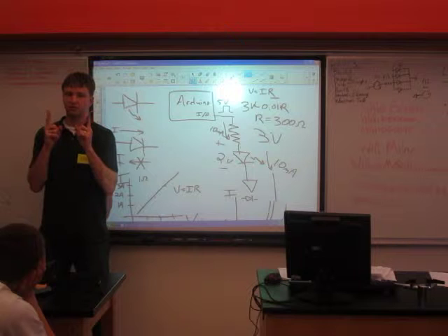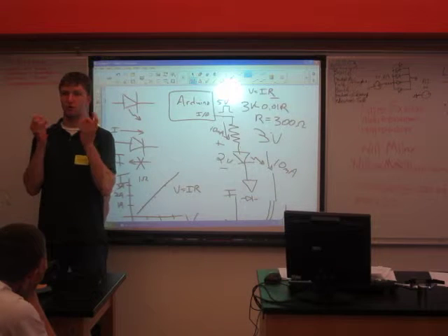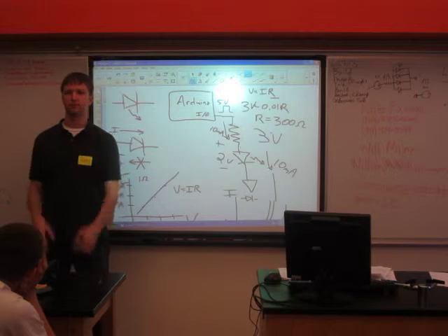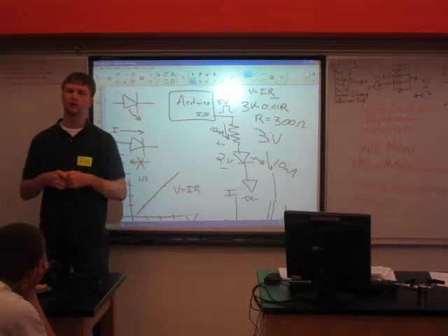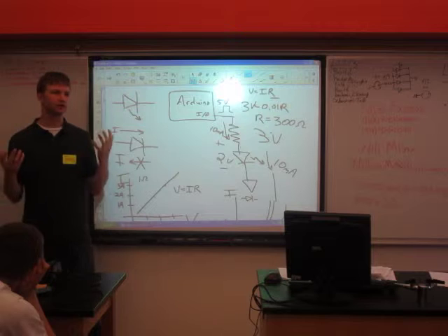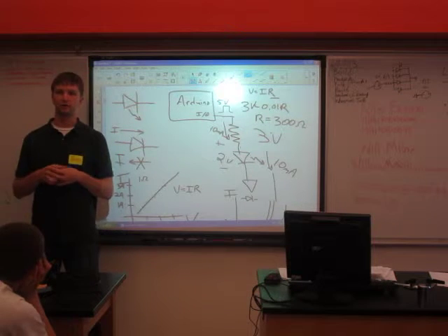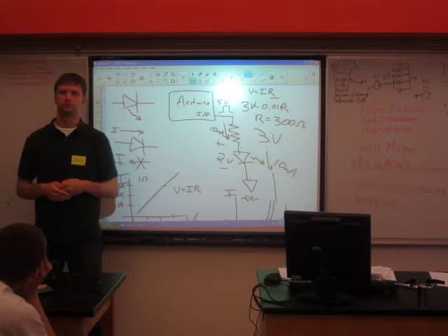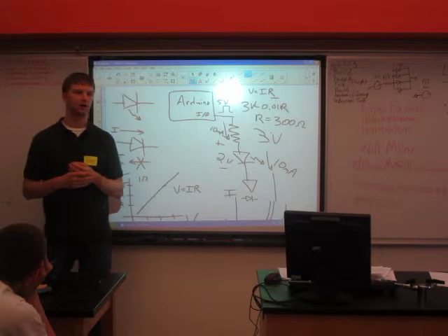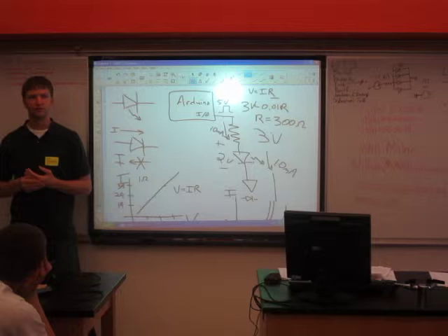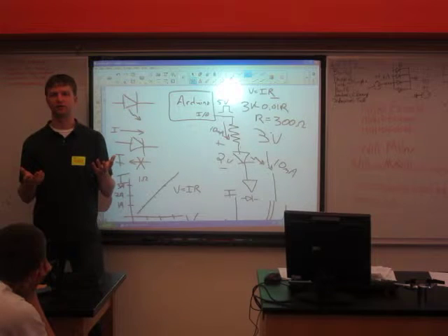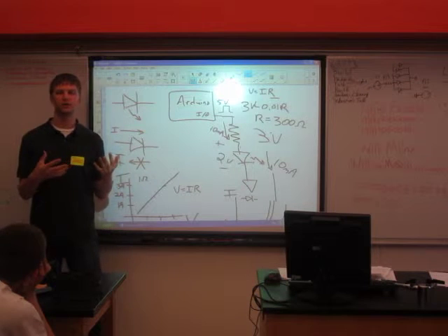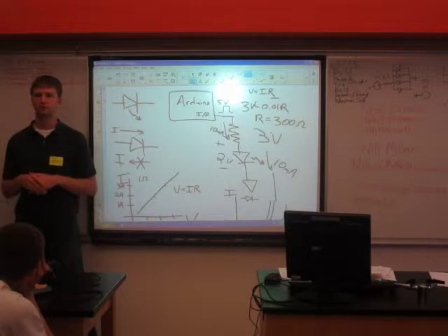So it's just a piece of metal that was specially designed so it would burn. And when it burns out, it acts like a fuse and it's over. That's why they're only 70 cents at the store, because it's a piece of glass and a wire. Super cheap, right? Unfortunately, since you're burning it, it's much less efficient. Most of the energy is going to heat, and a little bit's going to light.